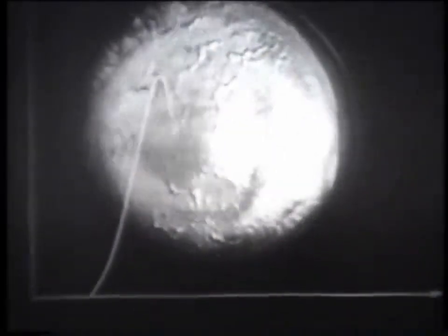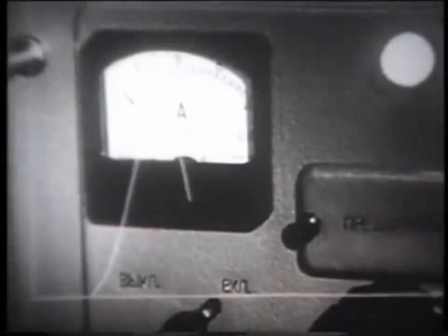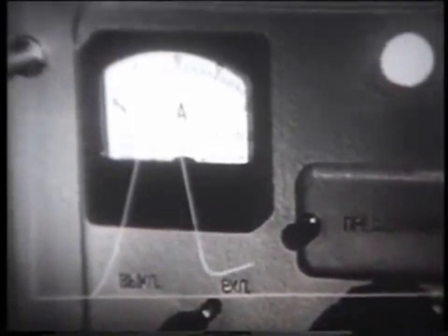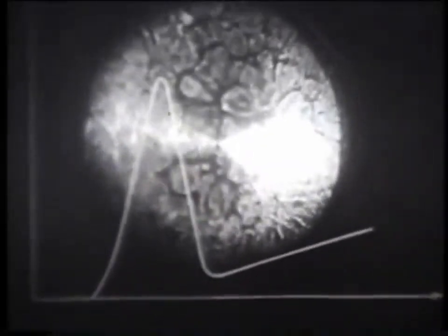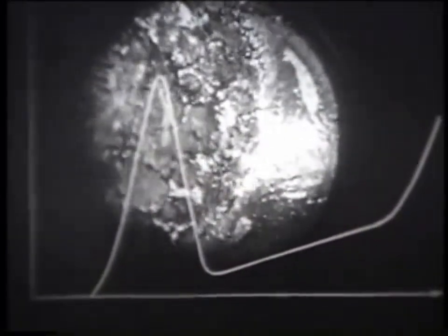The processes occurring on the anode can be represented using a polarization curve. The rate of dissolution, proportional to the current density, increases with increasing potential. However, with increasing polarization, the density of the anode current decreases, and a passivating film appears. The rate of dissolution of the metal is sharply reduced. At higher values of the anode potential, higher valence oxides are formed, which are easily removed from the metal surface.